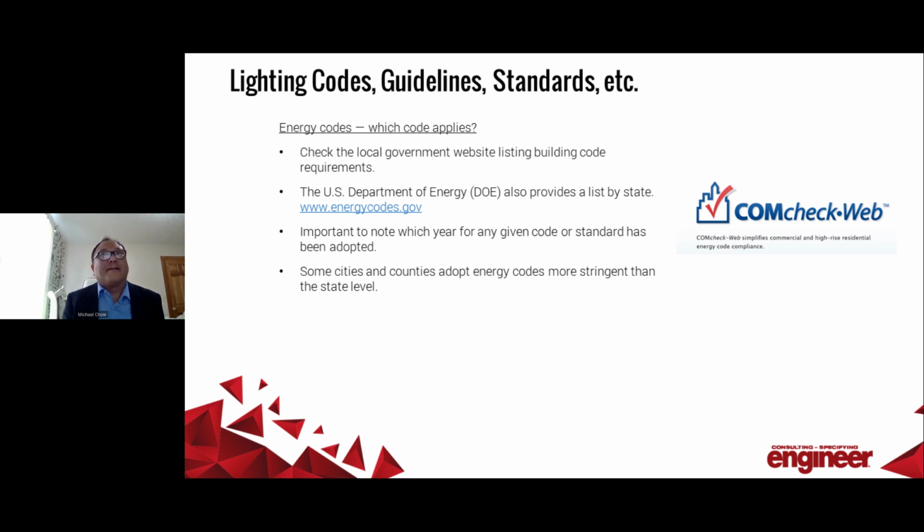Yeah, so I'll take just a little short story here about what we deal with, especially in Nebraska. We had a situation where the state code was recently updated to the 2018 IECC, and we have this exemption in Nebraska where if a renovation project is under 50% of the insured cost of a building, you're actually not required to meet the state energy code. So we had situations where the state energy code was the 2018 IECC, and many local jurisdictions had the 2009 IECC.